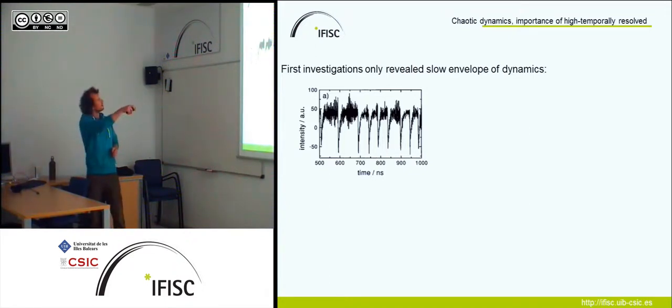You see these low frequency fluctuations, where you always get a drop in power and then it builds up slowly, and then you get a drop in power. All these drops are when the laser collides with the anti-mode and then gets re-injected close to the solitary laser mode. The time scale here is hundreds of nanoseconds.